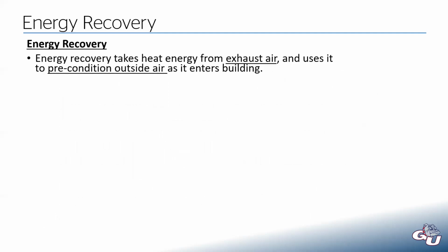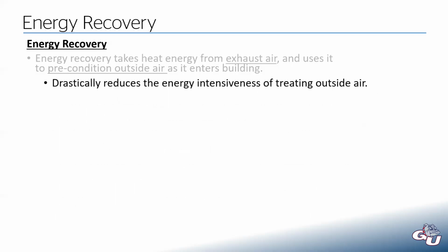What an energy recovery system does is it takes heat energy out of your exhaust air that you're dumping outside and uses that energy to precondition your outside air as it comes into your building. And this will have a drastic reduction on that energy intensiveness of treating that outside air that I've mentioned so many times.